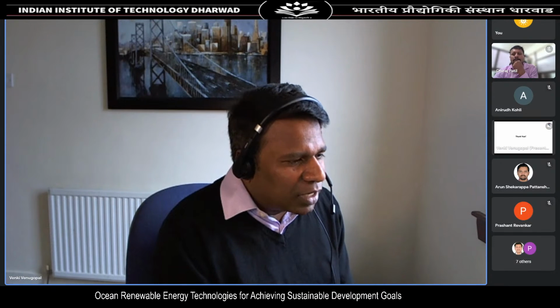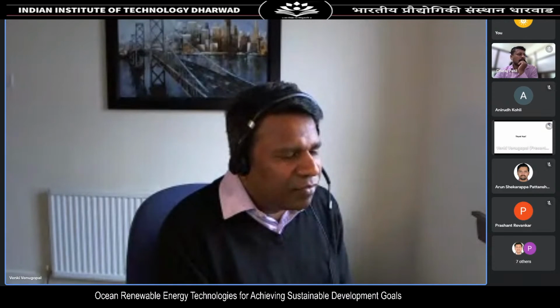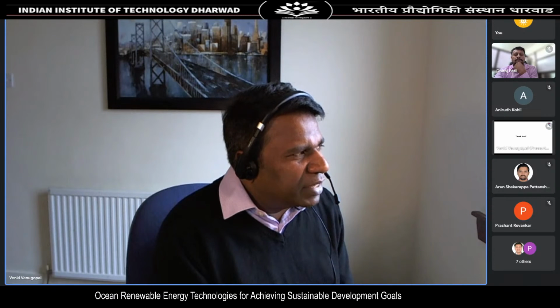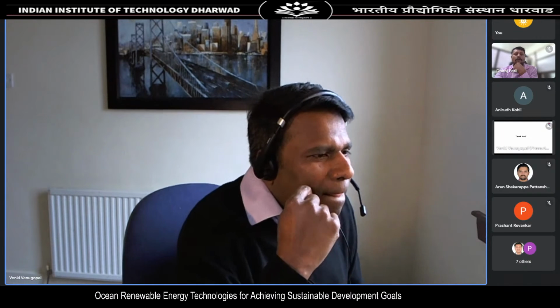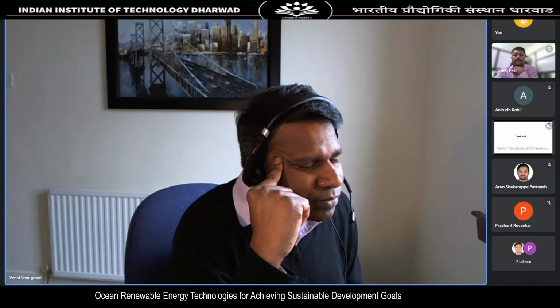For a wave model, it could be up to 0.8. So in order to satisfy the CFL number and also to capture everything that is going on there, we have to go for very fine scale meshes. The mesh size I used at the device location is 10 meters, and then it got bigger and bigger. So the smallest mesh size is 10 meters.